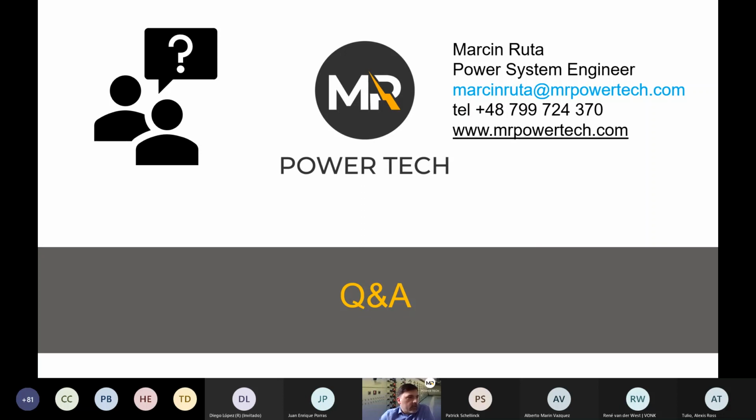What is the IEC standard for arc study, and what should be the minimum voltage requirement to perform an arc test? Okay, there is no IEC standard for arc study. We can only follow IEC 60909 for short circuit current calculation, but IEEE 1584 is the standard that we also use in Europe because it's international, it's not US related. I don't know what you mean by minimum voltage requirement to perform an arc test. If you mean testing the PPE, it's 2 kV if you do it as an open arc, and if you do a box test, it's 450 volts, I think.